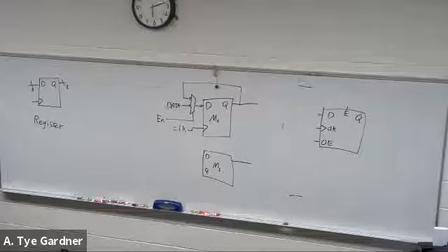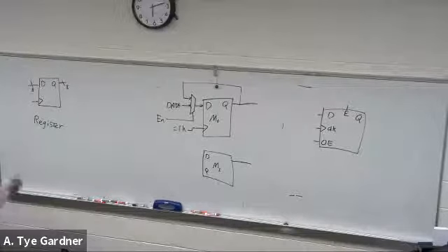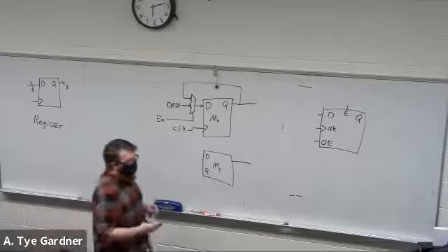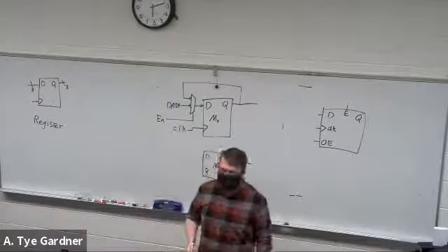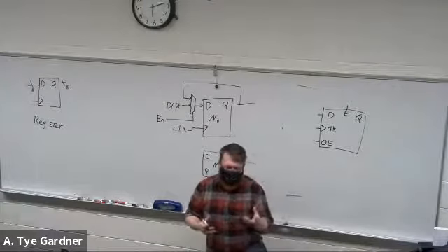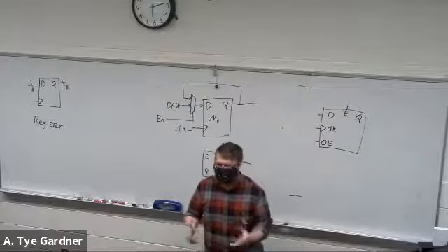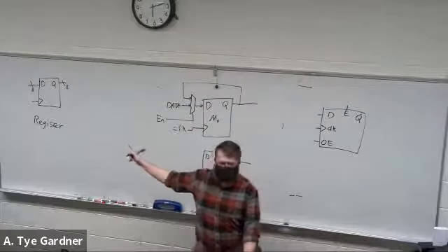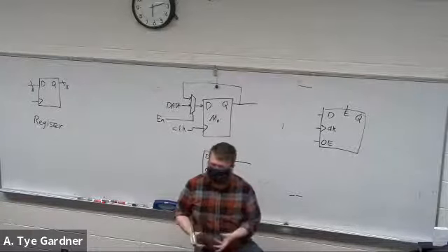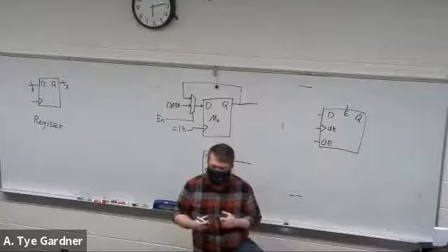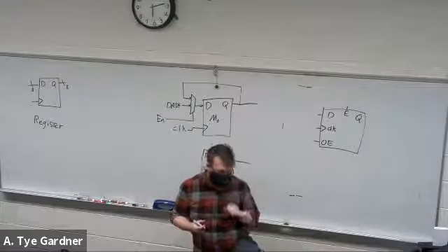You're going to hear this term a lot. This is like the basic fundamental building block of all what we would call cache memory. These registers are part of what defines processors. So if you got an ARM processor, ARM is just one form of architecture, it's going to be 8-bit or 32-bit or 64-bit. What that means is how many D flip-flops does it have in its registers? When it tries to access its memory, how many bits does it pull in at a time? That's what the register is telling you.